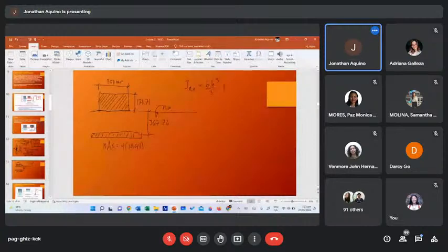Okay, so for this, we have no dimension. We don't have b, we don't have h. Although it has an effect, compared to the dimension of the beam it is very small. For our steel bars, our assumption is that this is the centroid, and you just spread it into an equivalent concrete section. It has no prescribed dimension. Okay? So we just assume that the centroidal moment of inertia of this is negligible, or very small, compared to the transformed moment of inertia about the centroid.